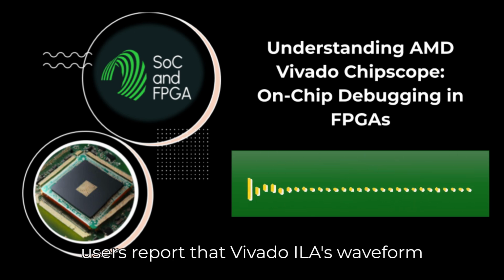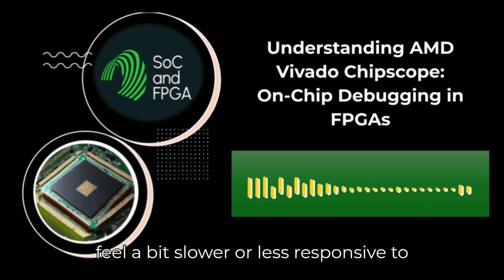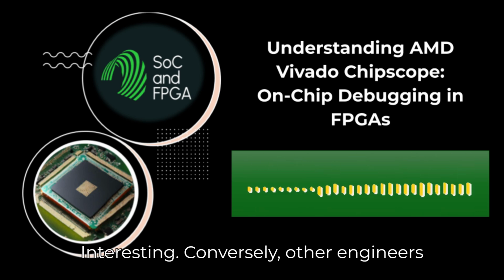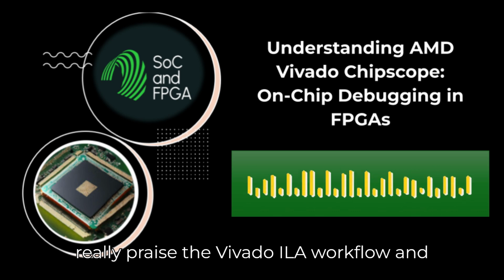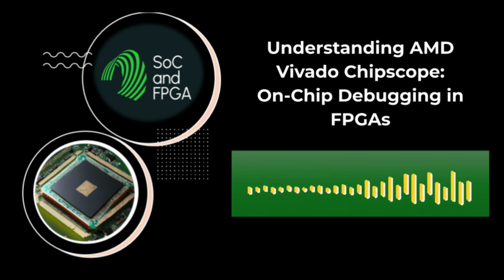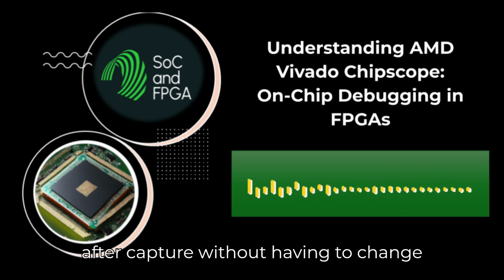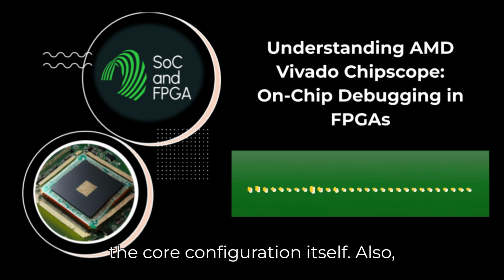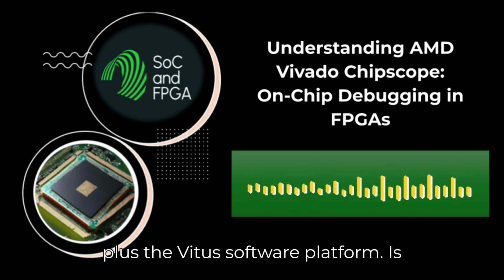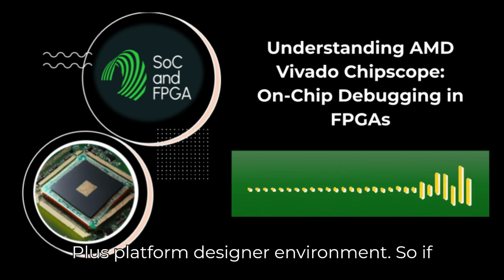Some users report that Vivado ILA's waveform viewer, especially when dealing with really large trace buffers, can sometimes feel a bit slower or less responsive to refresh compared to SignalTap. Interesting. Conversely, other engineers really praise the Vivado ILA workflow and the logic of its GUI, sometimes saying it feels leaps and bounds better, particularly mentioning flexibility in how you can modify the waveform display after capture without having to change the core configuration itself. Also, the overall toolchain integration, Vivado plus the Vitis software platform, is often perceived by users as perhaps more tightly unified than the Intel Quartus plus Platform Designer environment.